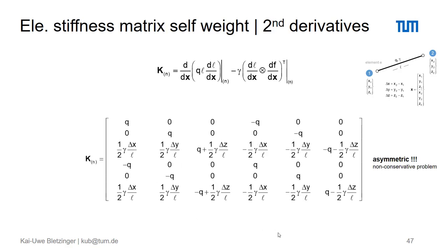The stiffness matrix in iteration step n, again, is the derivative of the residual force vector components, as explained before. And you see the entries are pretty condensed at the very end. On the main diagonal, you just observe the force density, as we got that from the linear force density method. And on the off diagonals, we just have the negative force density.